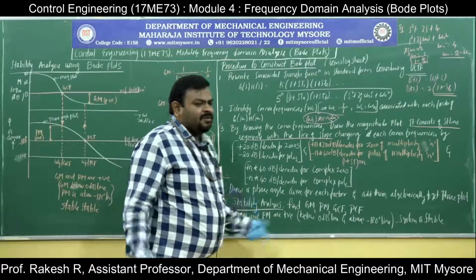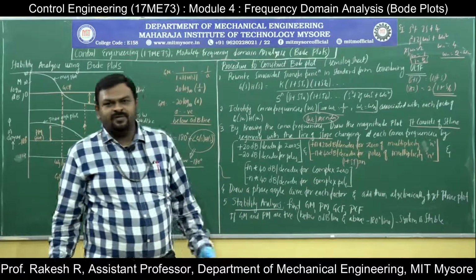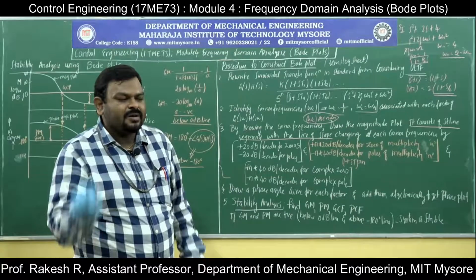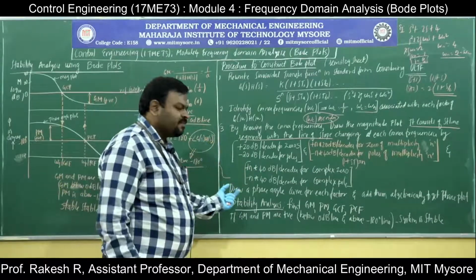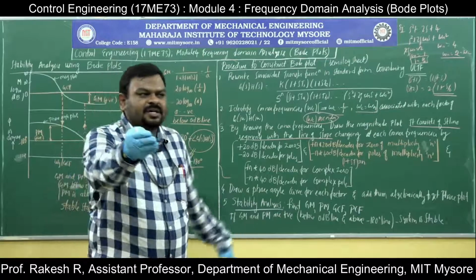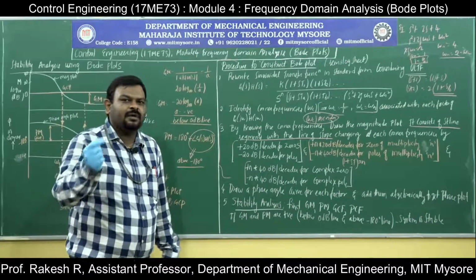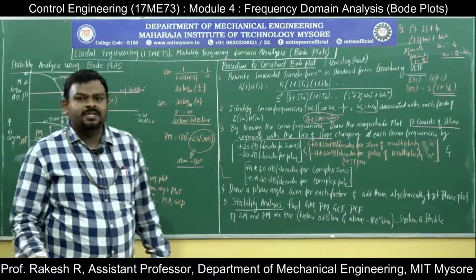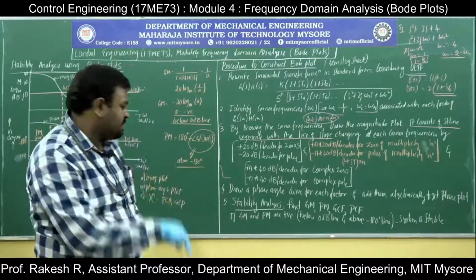Again, what is the calculation of phase angle that you know? Phi is equal to tan inverse of something, something, something. The procedure which you have solved in the Nyquist plot is the same. Directly write the equation for the phase angle and solve that using your calculator. There is an option called solve. By giving the values, you can get the phase angle for different values of frequencies.